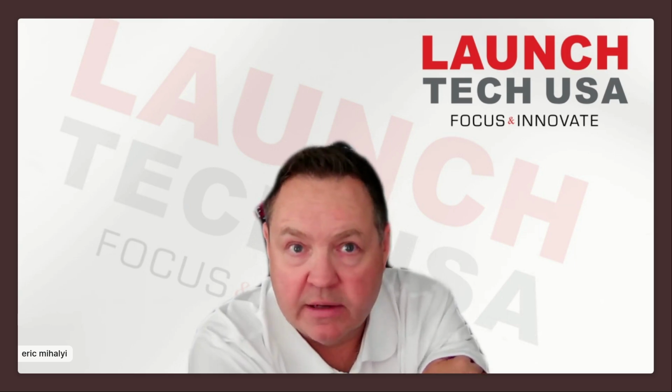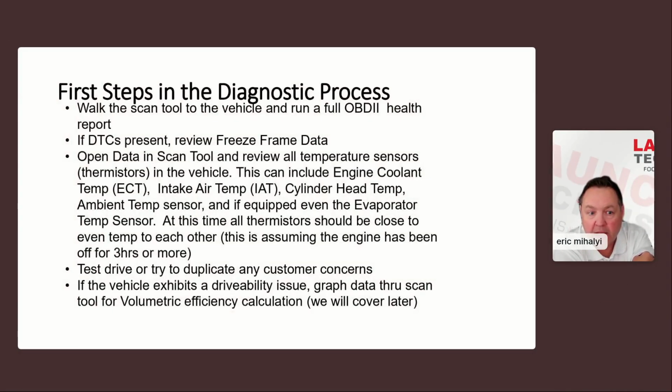So I followed this diagnostic procedure to a T, right? Every time, every car. And I'll explain why. So the very first step I do is I walk the scan tool out to the parking lot to the car. Okay. Key on, no starting the engine, and I look at a full OBD2 health report, right? And there's going to be a reason, I'm going to explain why in a couple of steps, why I don't start the engine at that time.